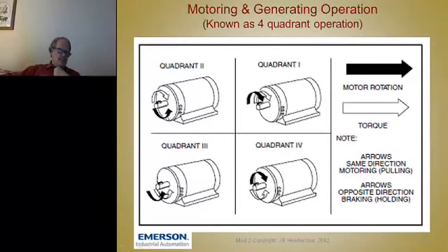put a shaft in it, put some arrows on it. A black arrow means speed, and the transparent arrow is torque. So as you can see in each quadrant, in quadrant 1 you've got clockwise torque and clockwise speed. Quadrant 2, when you're braking, you've got clockwise speed, but you've got counterclockwise torque.